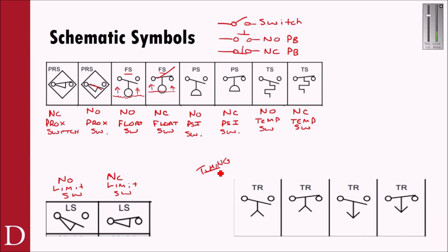And now these are some of the timing contacts. You'll have to remember back, but we used some timing relays in this lab. So I'll designate these with the acronyms, but pay attention to what I write here. You can see this is normally open, and you'll see the direction of the arrow. This is normally open, timed to close, NOTC. Drawn normally open, and the action is going to be in the closing direction as signified by that arrow.